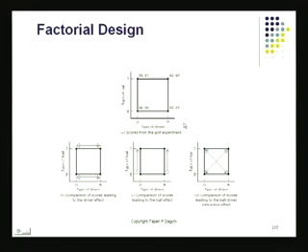So I've drawn basically a matrix which has minus, minus, minus, plus, plus, minus, and plus, plus. This is a matrix structure. This is a matrix discipline basically. And this is called the full factorial plan when I'm using two factors at two levels each. If you cross them, you end up with 4 combinations, and that's exactly what we've covered in doing this. Now this approach is okay if the noise variables don't have too much of an effect. Will you say noise had no effect?